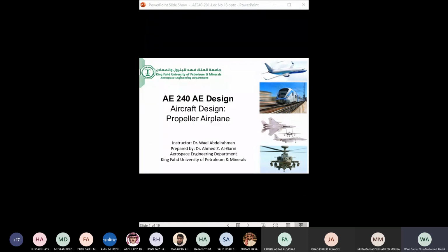But that's for the airfoil. For the aircraft or for the finite wing, you will have to multiply by 0.9. Don't forget that. Okay? And that's without the flaps. If there is a condition on the takeoff distance, the flaps have to be included as well. Okay, thank you. Any other questions?